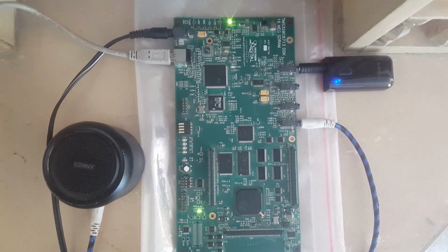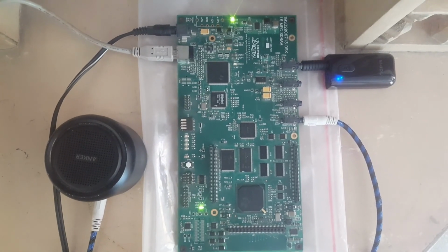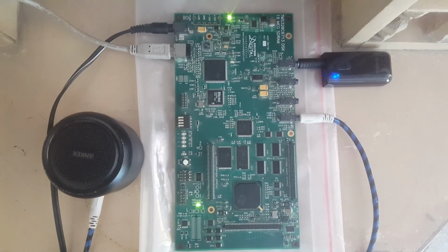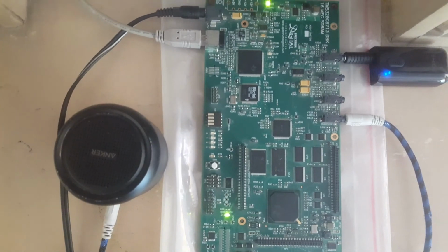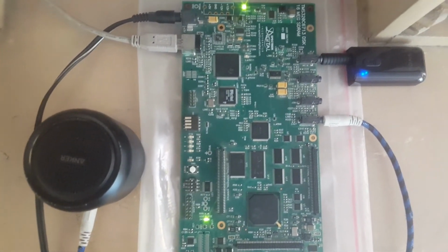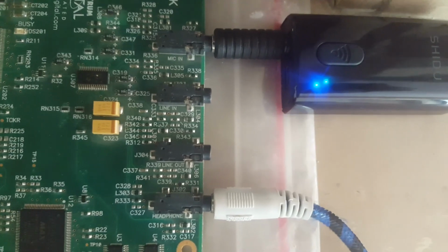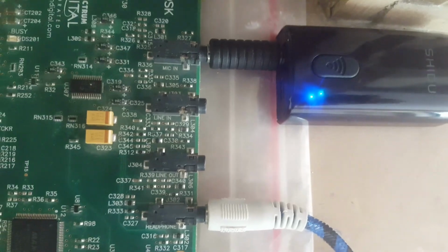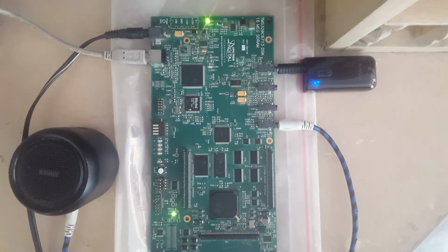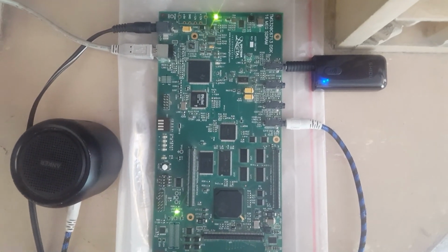The setup on the DSP kit has now been changed in such a manner that the mic in has been connected to a microphone line, so that we can get our audio, and the output line from the headphone has been connected to the speaker in similar fashion as the last lab, through an auxiliary cable. We can see the connections here. The mic in has been used for the input line, and the headphone has been used as an output line. Now, as soon as I press the resume button on the CCS debug window, I'll start hearing my voice from the speaker as well.